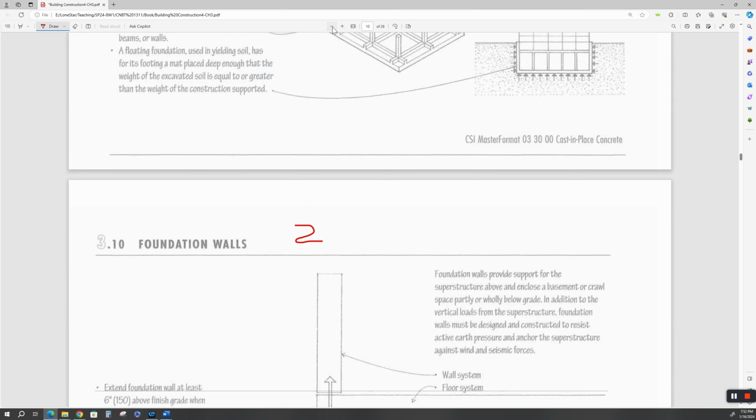So we don't know how big this is. We don't know how far this span is. There are other ways to handle this than just a sealant. Okay, you could use a PVC water stop, which is flexible.